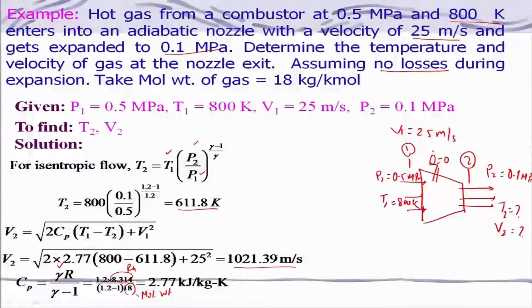Whether I can assume this density at the inlet and exit of a nozzle to be the same, that is possible provided it is an incompressible fluid. If it is a compressible fluid, then we cannot. Okay. Are you getting my point? Now, how will we know whether it is a compressible fluid or not? For that you need to of course go for the compressibility factor, from that you can find out the speed of sound,